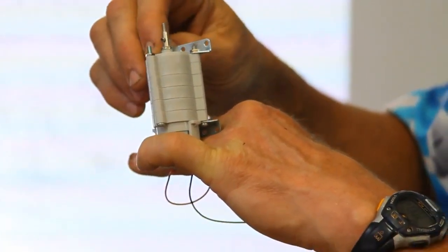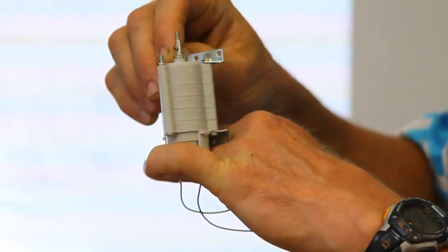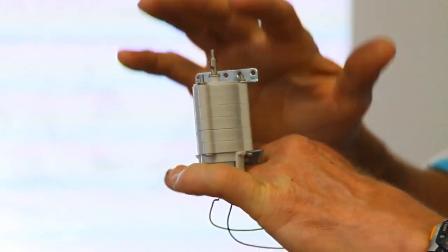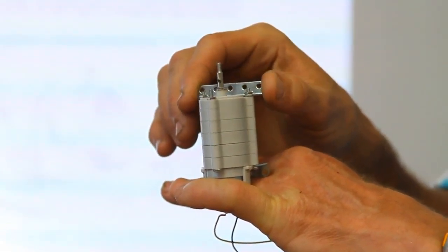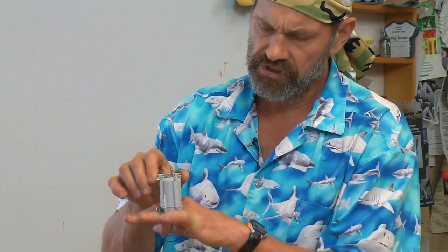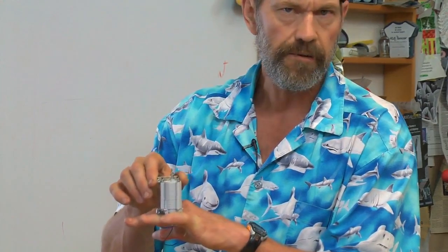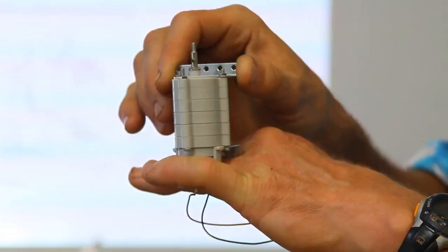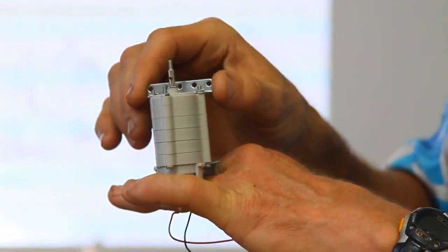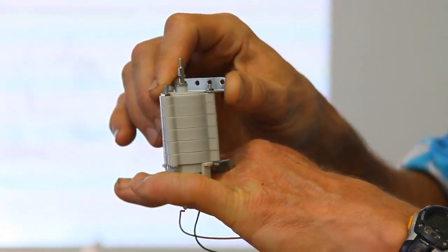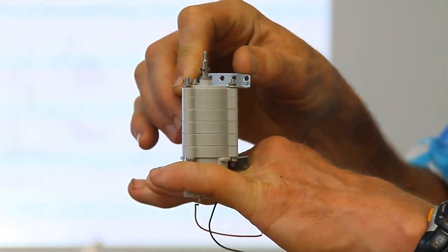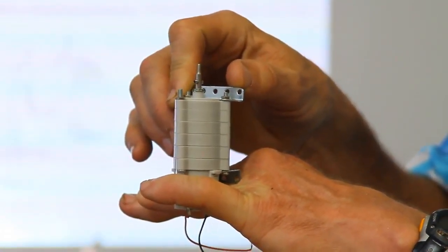We used these gearboxes in this design contest for many years because they were very low cost, easy to get, very nice, simple, modular. But a lot of students were very frustrated with them because their gearboxes just didn't seem to work very well, where the buddy next door to them worked great. And we always told people you've got to be really careful when you put them together about alignment, because if you bolt it together misaligned, the gears don't work so well. Bad.